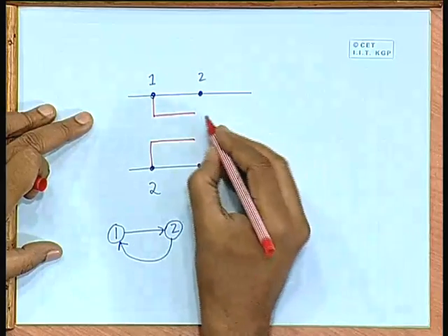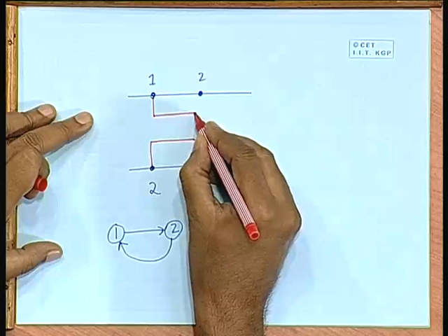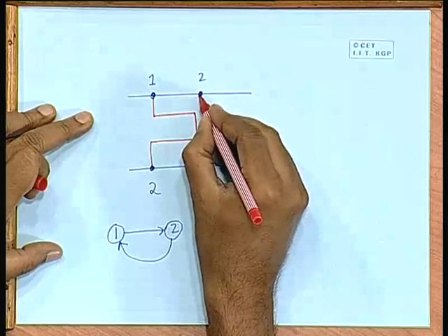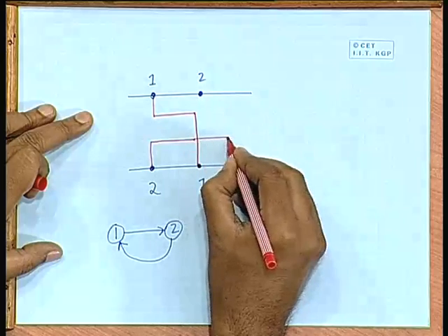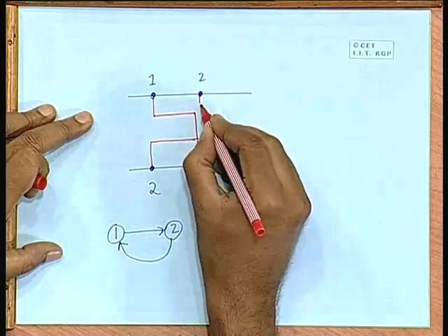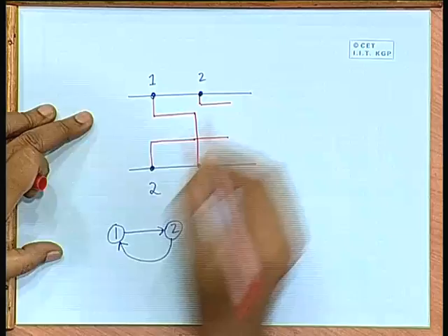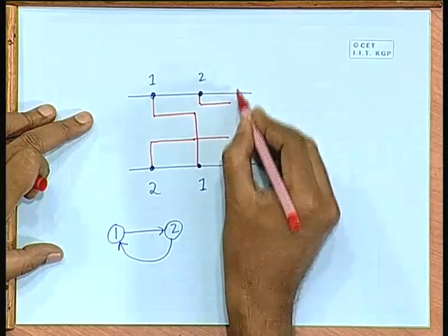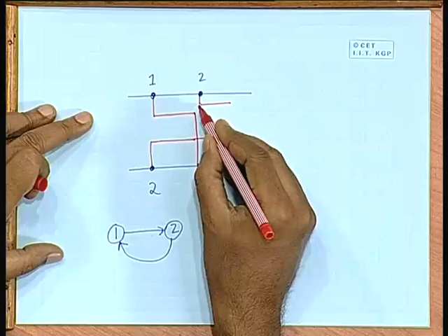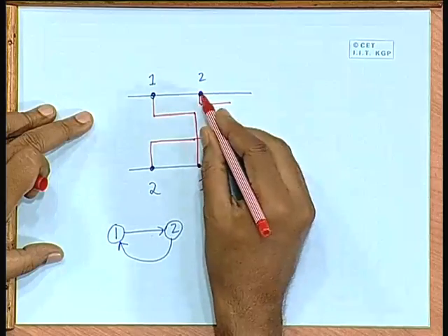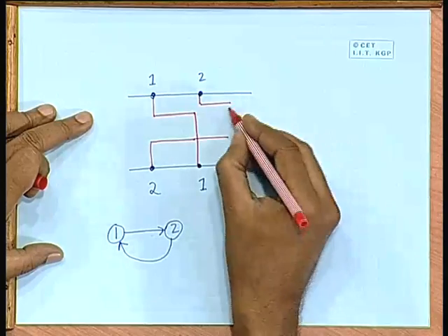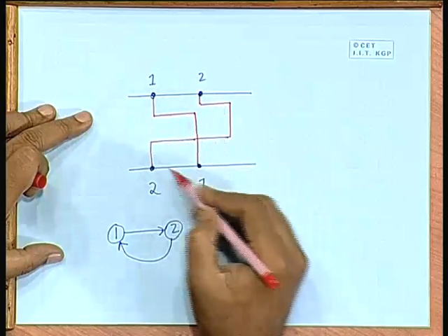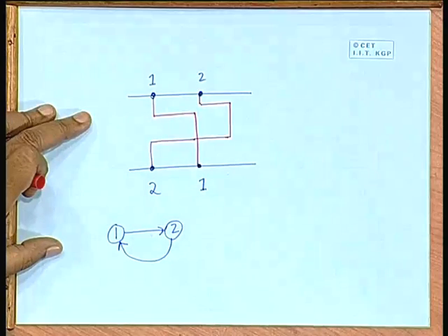So, we connect one of them, and from the other point let another net proceed to the right. Now, when we arrive at the next column position, these two net segments which belong to the same net 2 will finally get merged. So, we will be getting a solution like this.